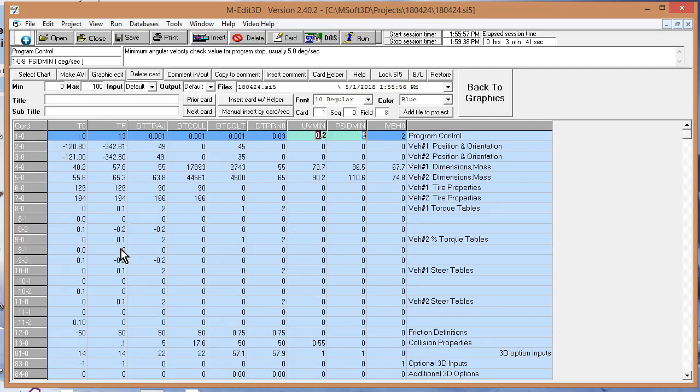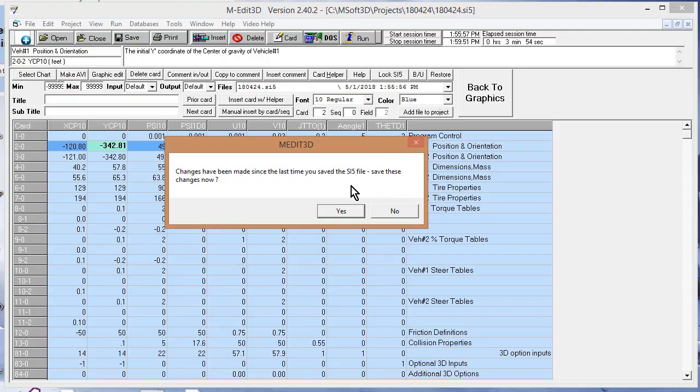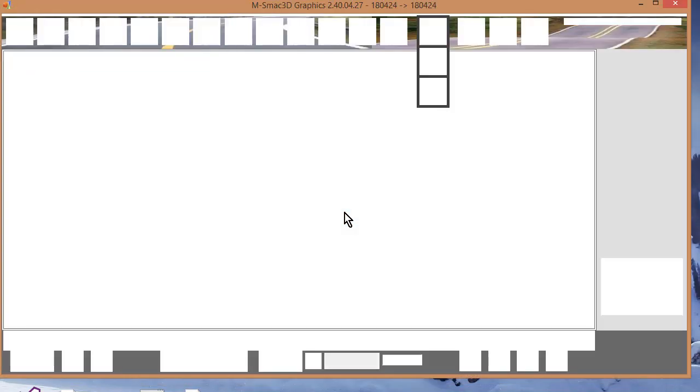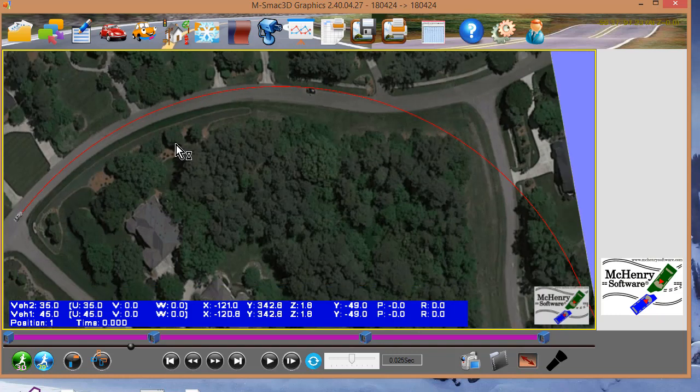Now, other thing I recommend when you first are setting this up, just set that to 0. In other words, you're running a 0 simulation, which is just going to show you the path, because in our graphics, in both 2D graphics and 3D graphics, it will show you the path. So we go back to graphics, and now there'll still be that path we had before, but now when I run it, and again, I recommend running it in 2D, you see how it shows the path.